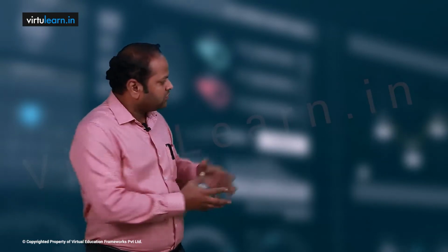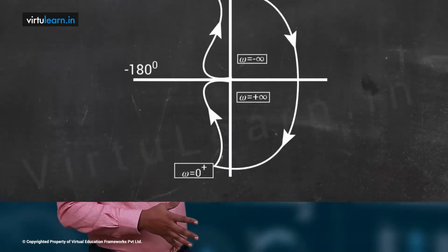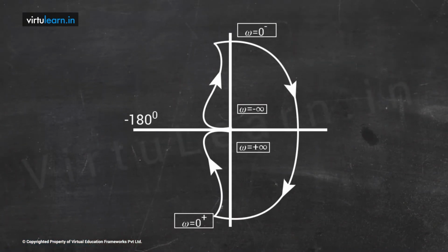So we have already seen all 4 paths: 1, 2, 3, 4. When you combine them, you will get the Nyquist plot. This is what the Nyquist plot looks like. This is path 1, coming from infinity to 0, and again from 0 to plus 90 degrees, again infinity, and with radius r tends to infinity a semicircle. So once you have the Nyquist plot, how do we find the stability of the system using the Nyquist criterion?